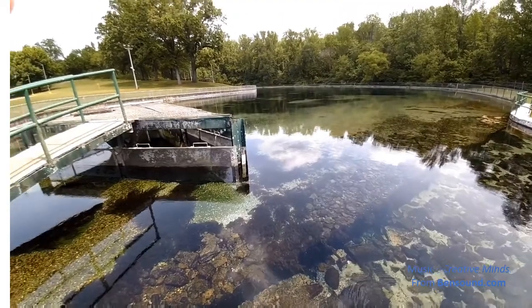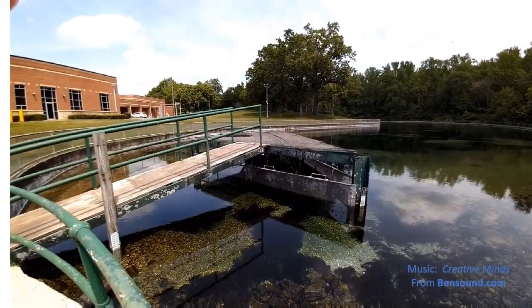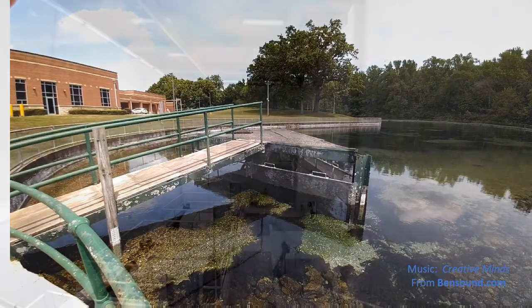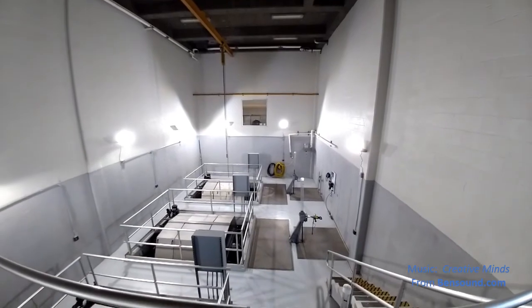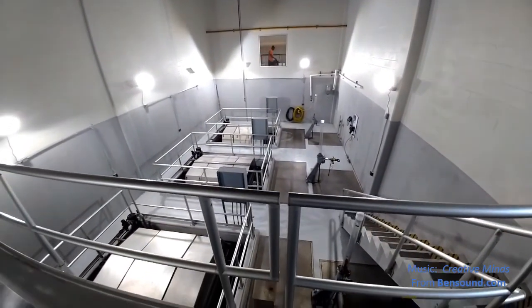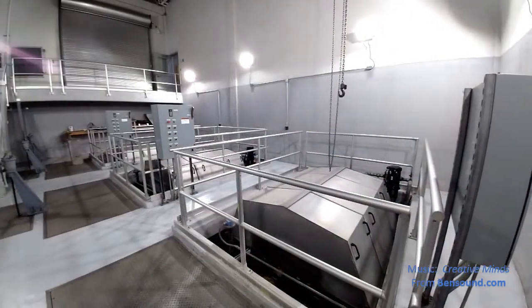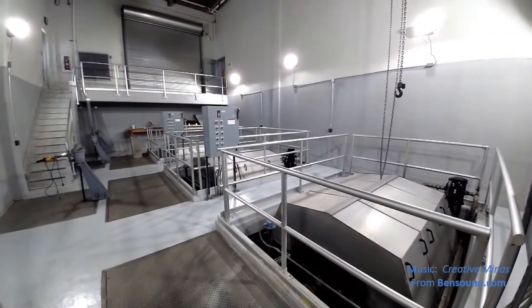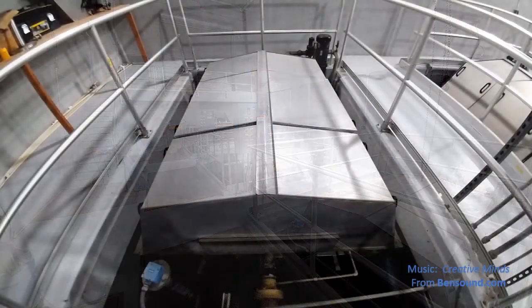The treatment process begins at the intake, where there is a coarse screen to prevent withdrawal of sand and debris. The water is then transmitted through a 48-inch diameter pipe to the microscreens. The microscreens have openings that are 100 microns in size. That is about the diameter of a human hair, pollen, or the point of a pen. The screens have a spray backwash feature to keep them clean.